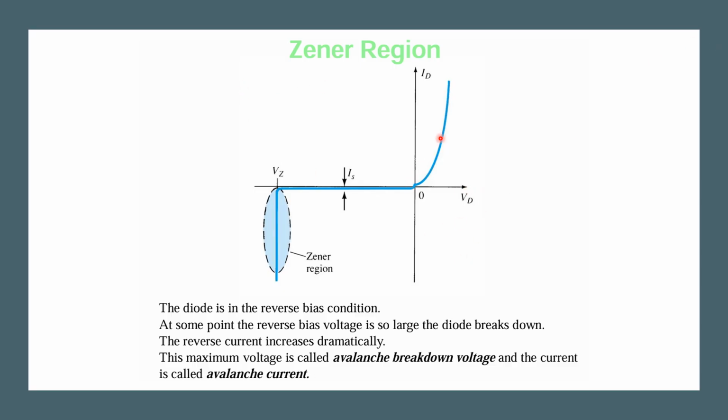See the forward characteristics here: they are the same as a PN junction diode. As the applied potential increases, the current through the diode increases exponentially. Coming to the reverse voltage, at a certain point, the breakdown point, as the reverse current increases, the voltage is constant. So it acts as a constant voltage source in the reverse bias condition after the breakdown.